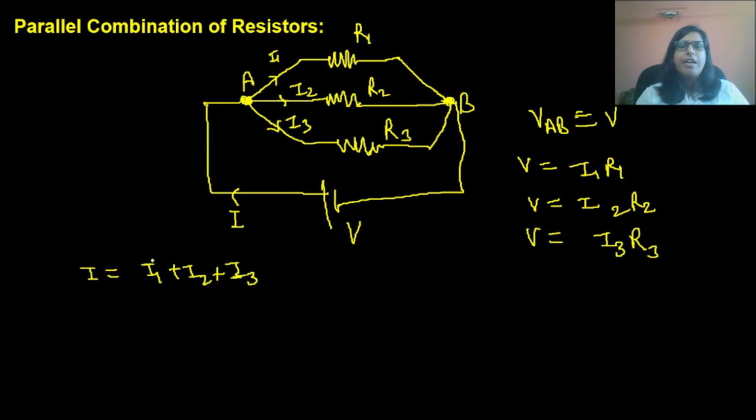and ahead we will see that this is the Kirchhoff law of current, right? At a node, total outgoing current is equal to total incoming current. This is the Kirchhoff current law and it is based on charge conservation. So now if we put the value, I will be the voltage upon R equivalent. From Ohm's law we know V equals I into R.